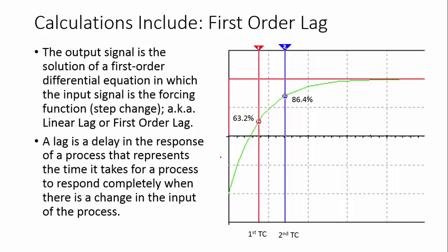The step change is shown with this red square wave, this red line right here. You can see that it went up, hiding behind a grid line, right at this point is where the step change occurred, this is the upper part of it, and this is where the new limit, or the new set point, is. The process now starts responding to that step change, so it starts to come back up to the new value.